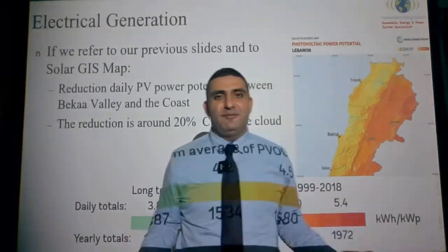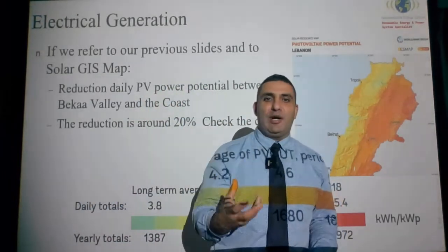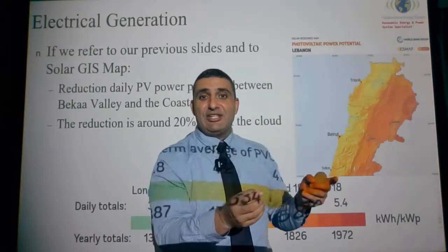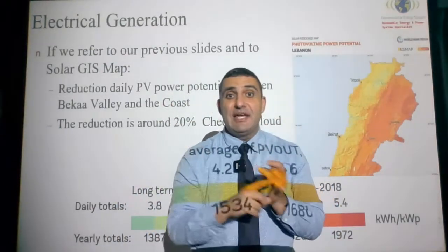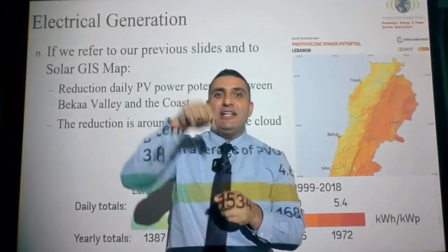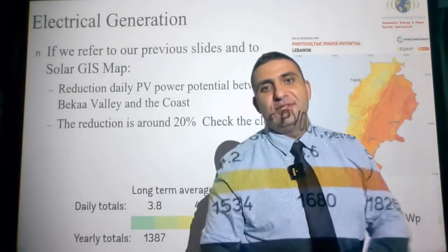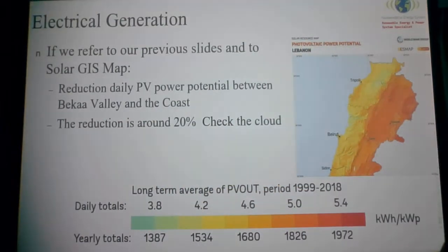It's not possible, because for 5 kilowatt solar panels to give you 5 kilowatt, according to the datasheet, you have to have 25-degree temperature, 1000 watt per square meter sun radiation, 90-degree angle on your panel. No obstacle, no disturbance.